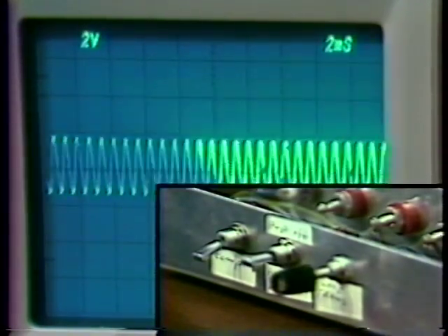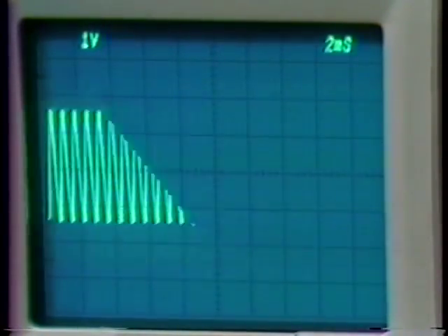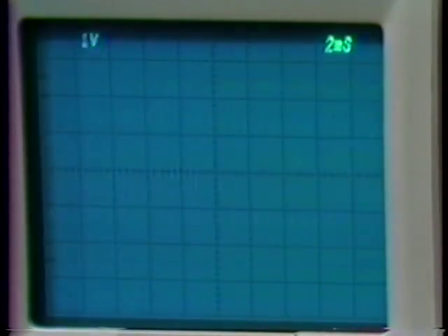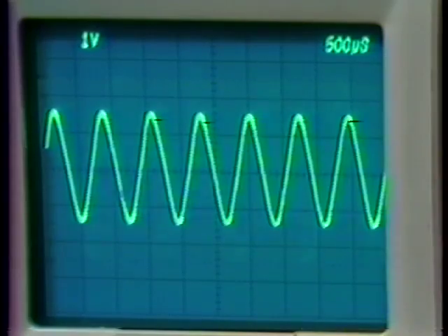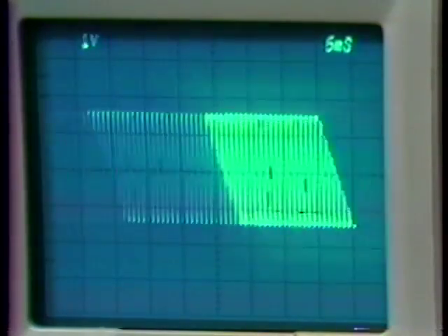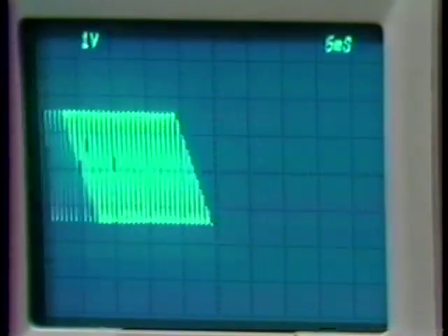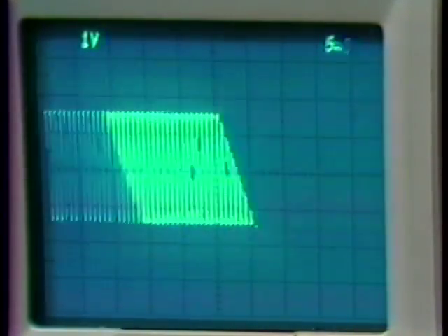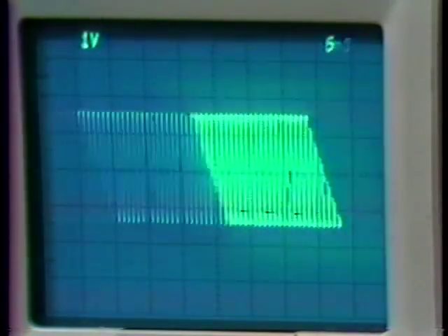Let's make the input signal go away completely. And we're now oscillating because we have too small an input signal. In fact, we can look at the frequency of oscillation, and we notice that it's out around a kilohertz. We're now oscillating at the higher frequency point. In this case, we can cure the oscillation, make it go away, by putting in a large signal. That gets the gain of our describing function element to be higher, and that cures the oscillation.